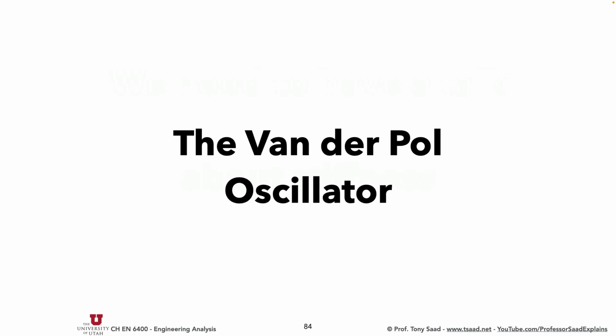Typically, what you study in physics is that the simplest model of a spring is that it reacts proportionally to the displacement. So you displace a spring by delta x, the restoring force is going to be a constant times delta x. But that only applies for very small displacements. Springs react linearly, k times delta x, when the displacement is small. But when displacements become larger, there is a nonlinear restoring force. And that's exactly what happens with the bridge, with the homework problem that you're working with.